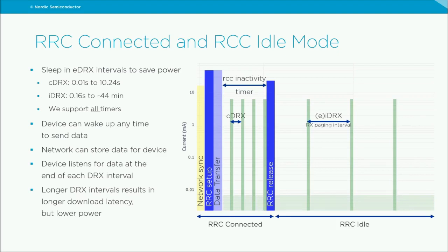consumption. One thing to note is that we support all the timers. There are some modems out in the field that do not support all the timers, but we have made sure that the Nordic nRF9160 supports all of them. And this means that you can have a device that can wake up at any time to send data, but for the rest of the time it can stay and listen through these paging intervals. And the network can store data for the device if it has that supported, or else you should have the server buffer up the data.